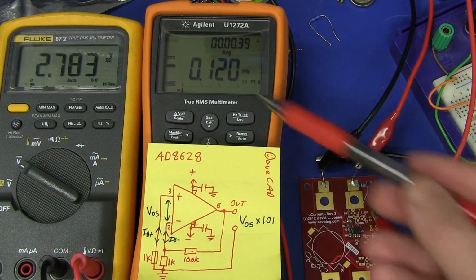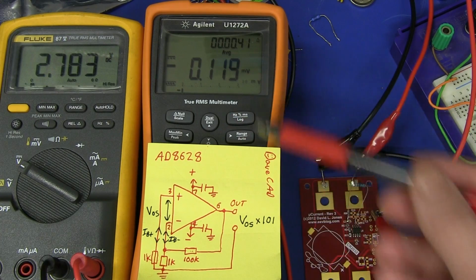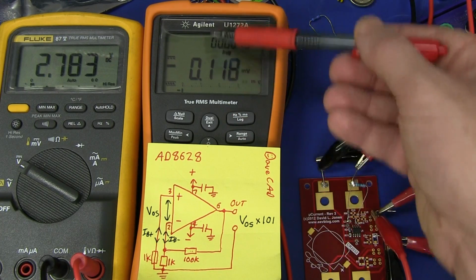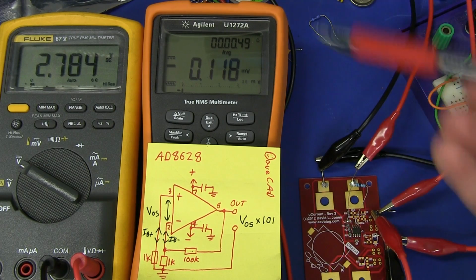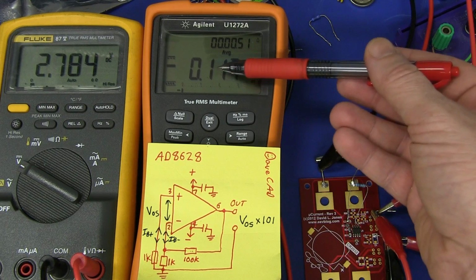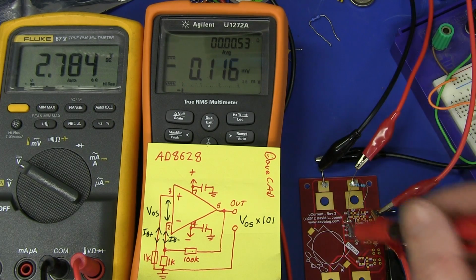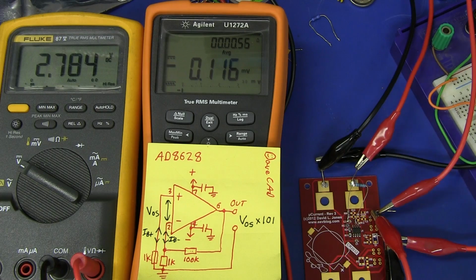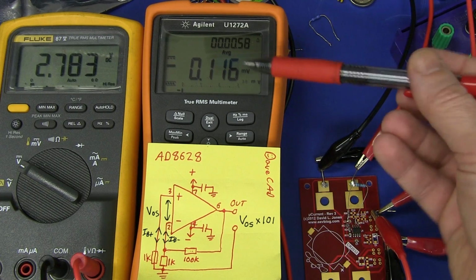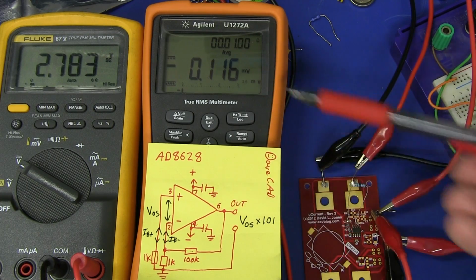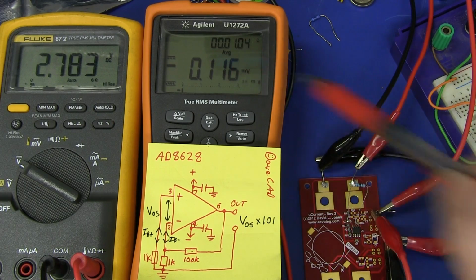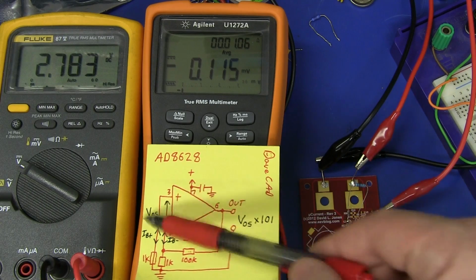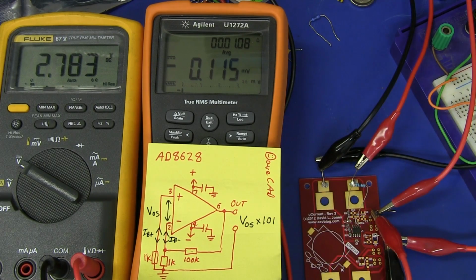By adding the bias resistor in there, we've done a pretty good job. I don't care if it fluctuates plus or minus like that over the supply voltage range. You kind of expect it to do that really, as long as it's within your acceptable margin. Before, when we were getting 300 microvolts, and in some chips I was measuring 500 microvolts, that clearly wasn't acceptable for my purposes. But this sort of range, plus or minus 100 microvolts or 1 microvolt of essential V offset combined,